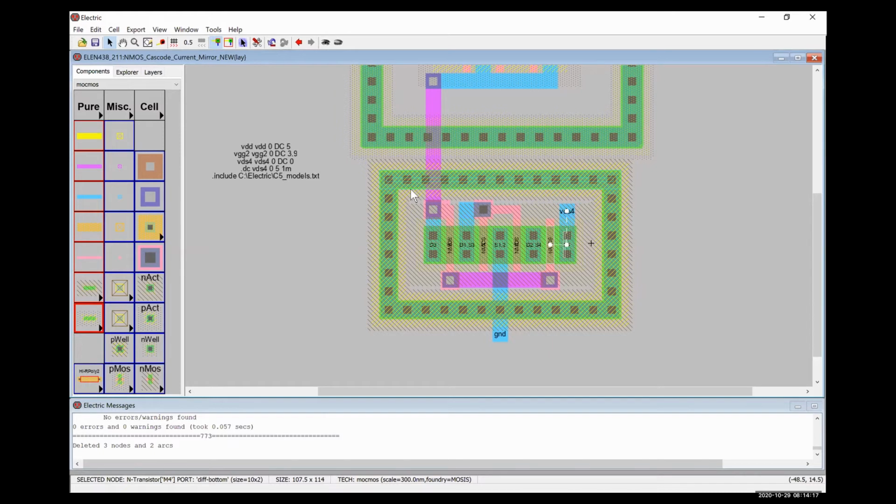Another question. Sure. For the metal 2 to metal 1 contact, the little purple square, does that just float on top of the metal 1 to poly contact, or does it connect somehow? I couldn't figure out how to make it actually connect. You're talking about this guy right here? Yes, sir. Let me move it out. So it is connected.